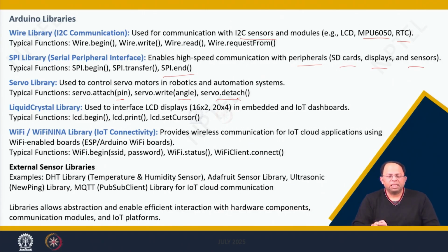Then the liquid crystal display library, used to interface with LCD displays, both in embedded systems and also in IoT dashboards. Typical functions are LCD.begin, LCD.print, LCD.setCursor, and so on.